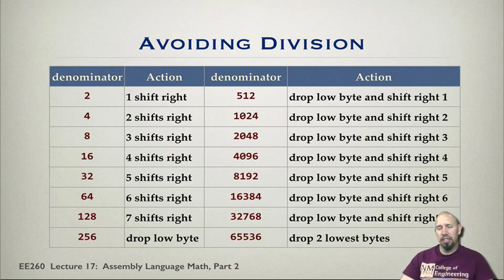This is actually doing division with these particular denominators. So we've now talked about integer ratios, and if we can use powers of 2 as our denominators, that makes it very simple. So, integer ratios: useful stuff when doing math on a limited processor like the Arduino.